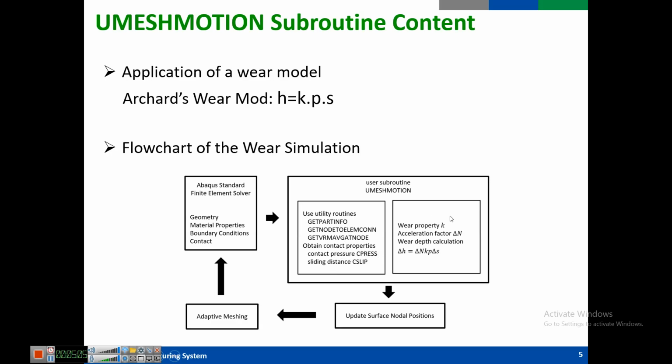And also you need to define wear coefficient and acceleration factor, or delta N, or jump cycle, to help you perform your wear simulation with less time than without jump cycle.